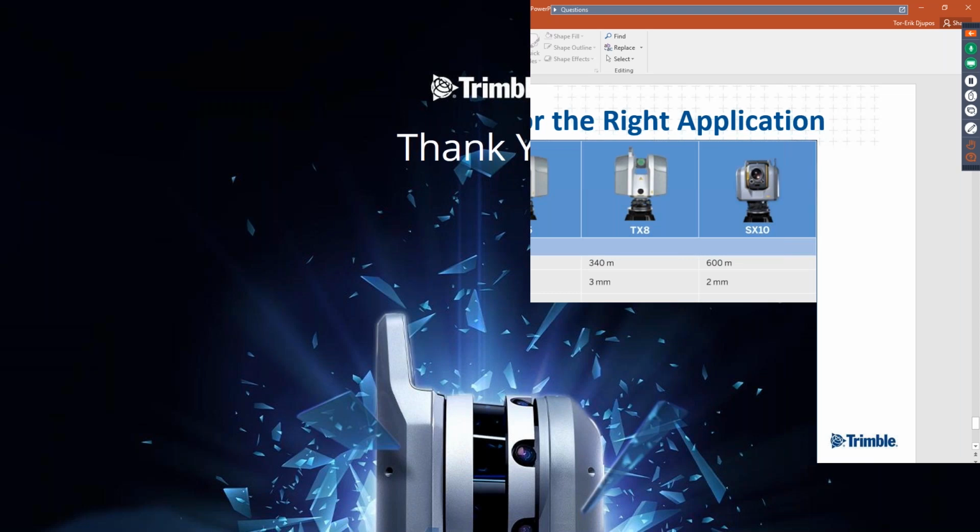Also, a question around the servicing, Ted. So, the statement is, so it never needs servicing. Yeah. Well, a service and calibration are two different things. A service can be the mechanical side of things. Calibration is the process, which is normally something you have to send back to a factory because of the tools needed to run it through, to take the measurements and apply these data, these deviation reports, all that kind of stuff, into the laser scanners.